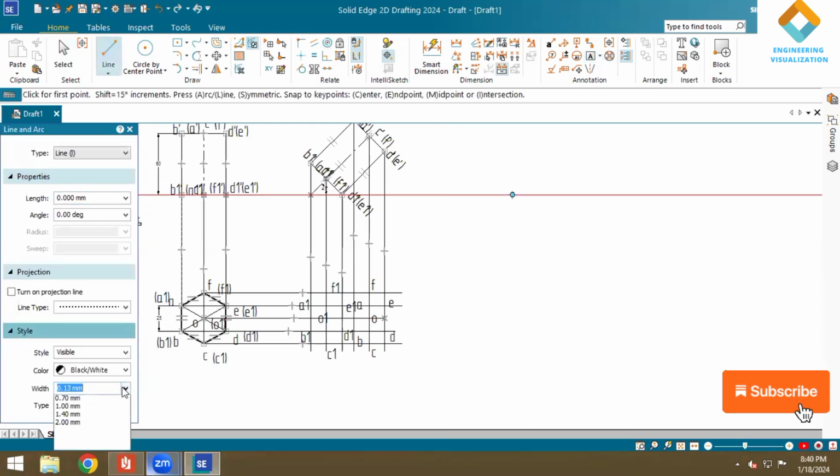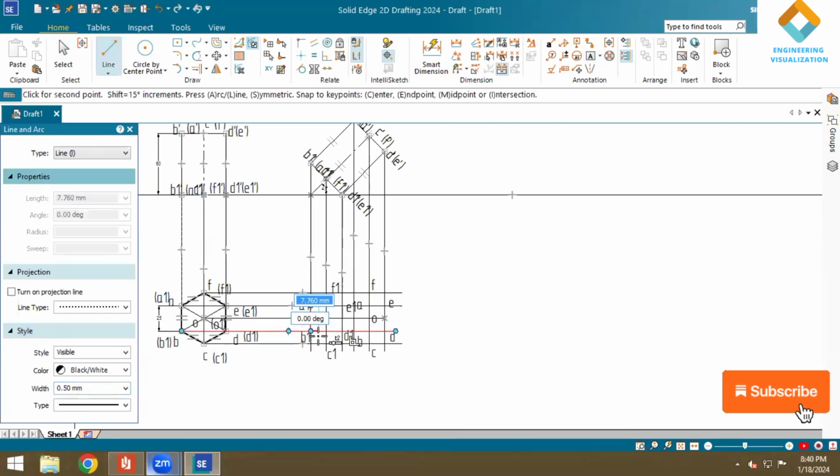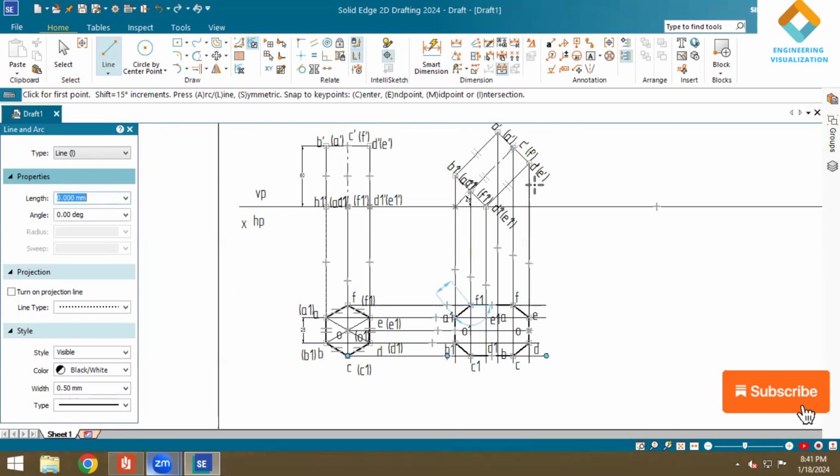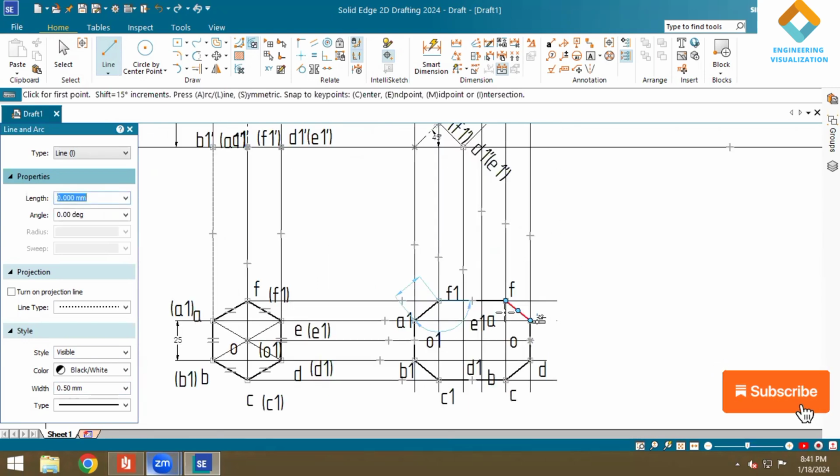To construct the second position top view, we know it has 3 steps. First step is constructing an outer boundary line. So join all the outer points. Now write the visible faces. The top face is visible. That means the top face hexagon is visible from the top view.